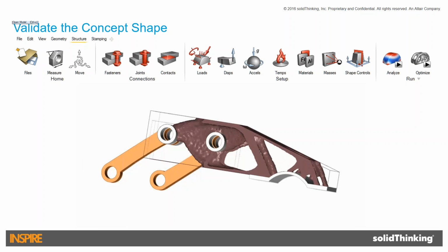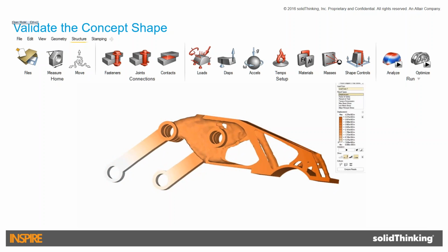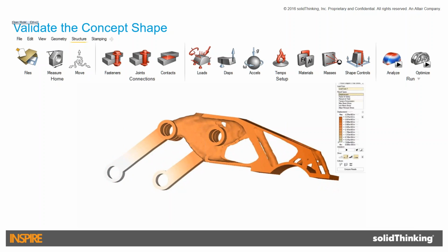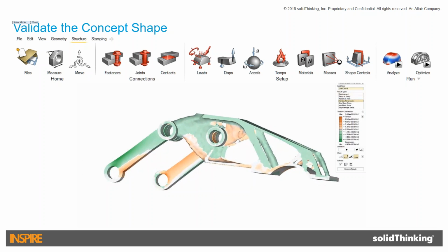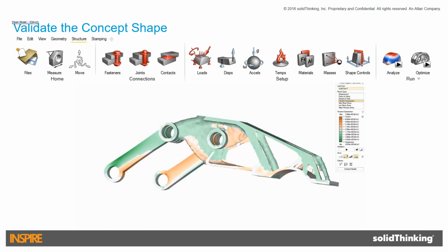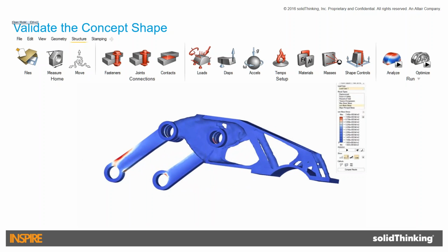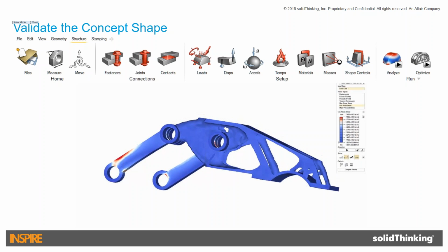Now before you actually start your detailed design work, one of the biggest benefits I see in Inspire is the ability to validate that concept up front. So maybe you created those 4 different designs we just looked at and we want to figure out which one's the best one to move forward with. Here we can do comparison studies on things like displacement, understanding tension and compression, factors of safety, and the von Mises stress throughout your components. And again, I haven't even opened up the CAD package to start a detailed design. So you're bringing analysis in at the very earliest stages.